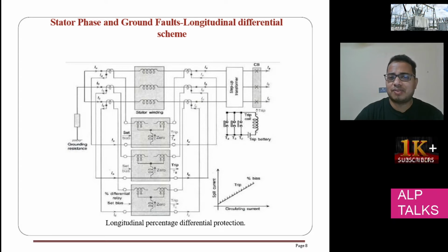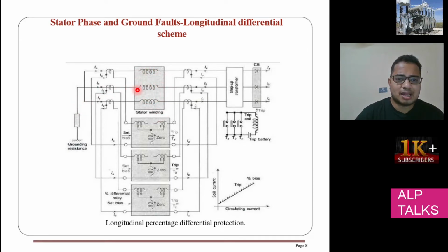Stator phase and ground faults, longitudinal differential scheme. So here you have the stator winding, you can see it here, whatever I am highlighting. The other terminals of the stator are grounded. We can say this is a star connected, so Y connected winding.